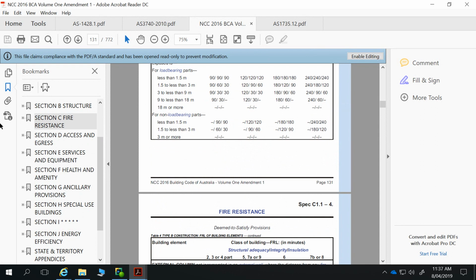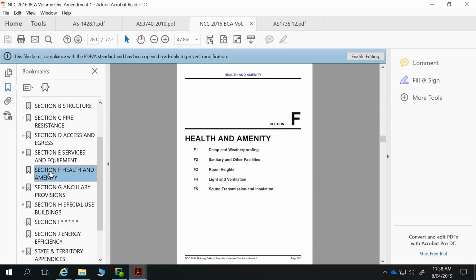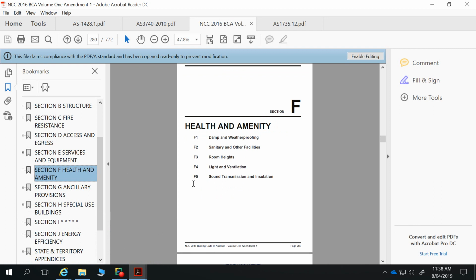Yes, you're definitely a bad neighbour if you set your neighbour's building alight, but another way of being a bad neighbour is to make lots of noise, and for that noise to be transmitted between units. Because of that, we also have to ensure that those separating walls are not only fire resistant but also have limited sound transmission. Did you cover any of this in compliance? Some people have met that sound transmission requirement, others haven't.